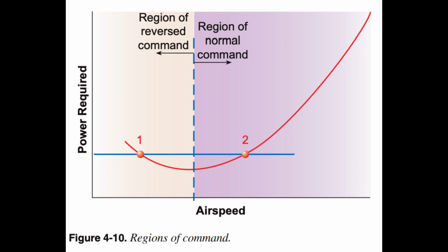Slow-speed flight. Anytime an aircraft is flying near the stalling speed or the region of reversed command, such as in final approach for a normal landing, the initial part of a go-around, or maneuvering in slow flight, it is operating in what is called slow-speed flight. If the aircraft weighs 4,000 pounds, the lift produced by the aircraft must be 4,000 pounds. When lift is less than 4,000 pounds, the aircraft is no longer able to sustain level flight and consequently descends. During intentional descents, this is an important factor and is used in the total control of the aircraft.